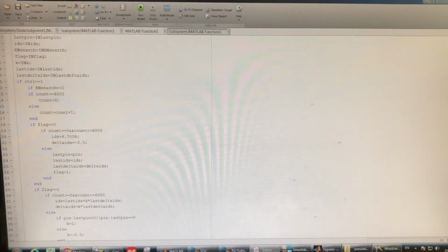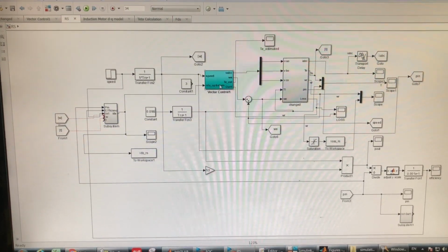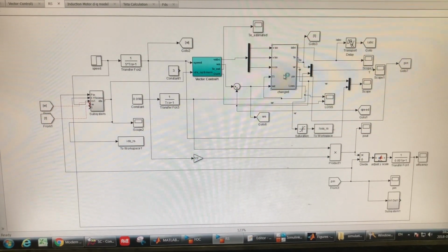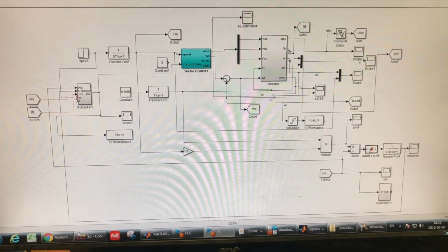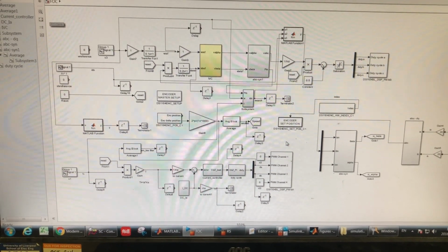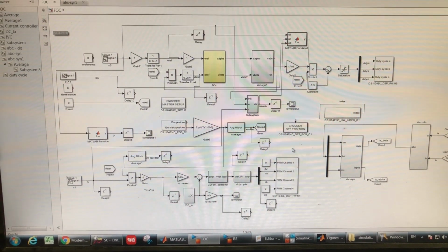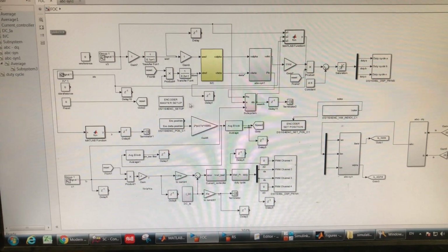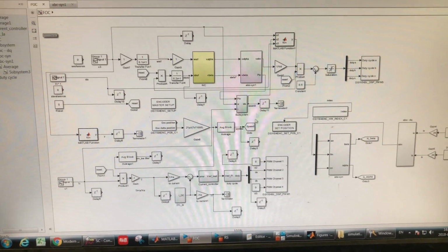here, and a vector control, general vector control block, but also a DQ module of the induction motor. To convert this to become an interface that can be applied to the DS1104 processor, firstly, we have to delete the DQ module of the induction motor.